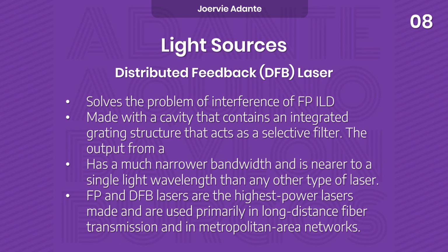For the DFB or distributed feedback laser, it solves the problem of interference of FP lasers. It is made with a cavity that contains an integrated grating structure that acts as a selective filter.